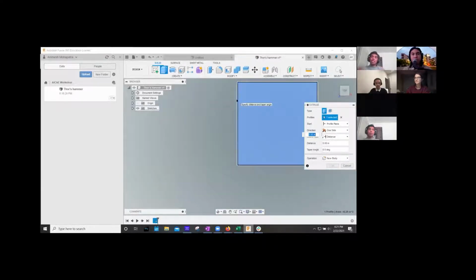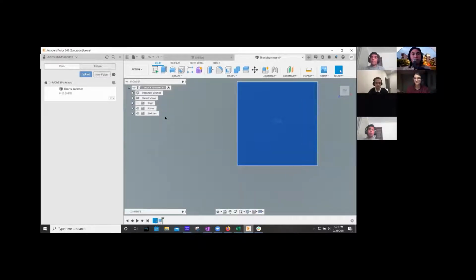This is going to stretch stuff out in the third dimension. This should automatically become dark blue or blue. And this number over here, which my cursor is flashing over, is going to be the height. That was 22.7 inches. It should turn dark gray once you press enter after typing 22.7. But right now you're thinking, what actually changed? Well, right now we're just looking at it from the top view, so we saw height increase in the top dimension, and you don't notice that.